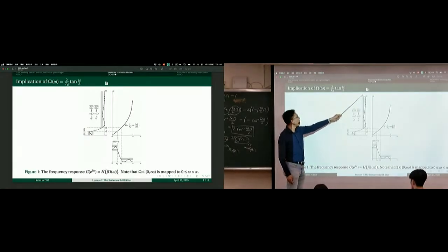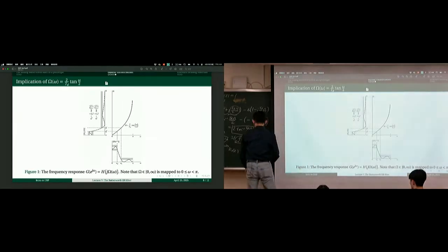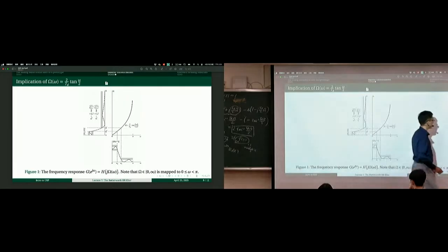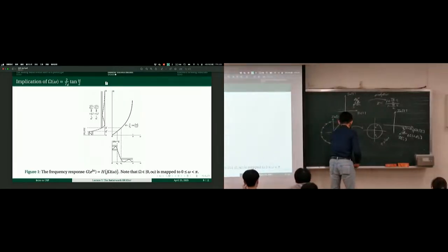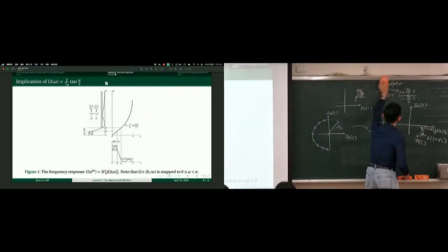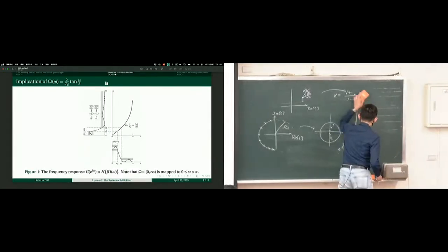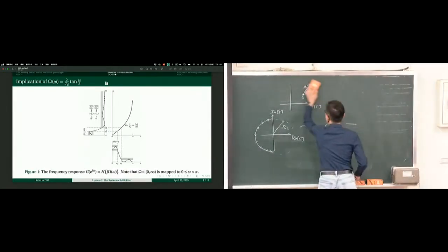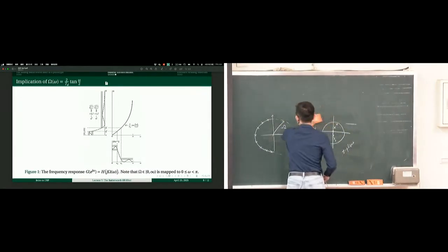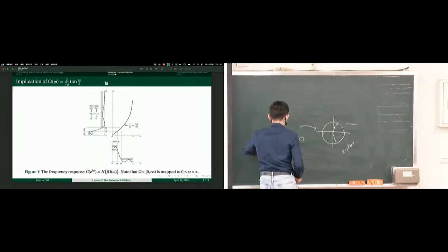But now, by using arctangent, the corresponding small omega is 2 times arctangent of T_D divided by 2 omega, big omega. Arctangent compresses the entire real line to a finite interval.